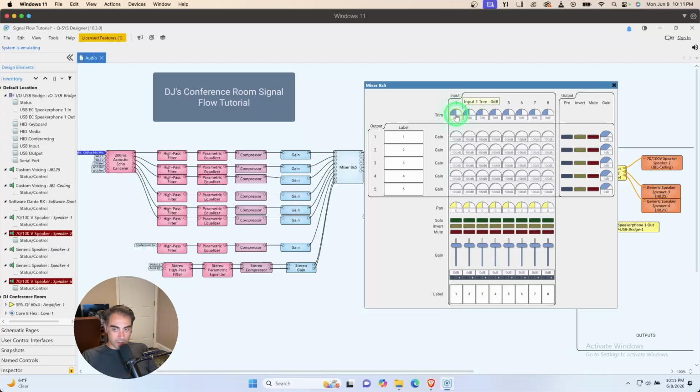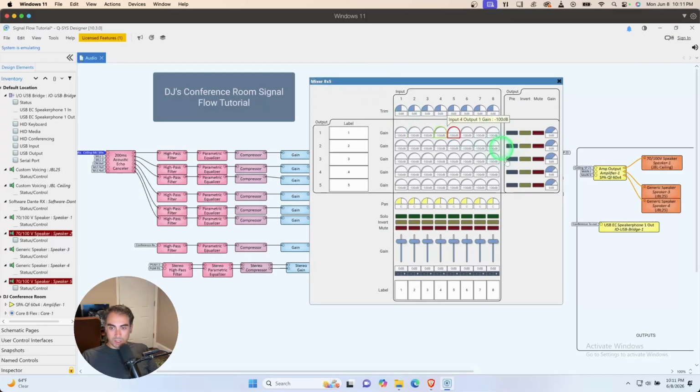Like, how on a mixing console your trim knob would be up top here, and then your post trim or head amp gain, and then outputs are going to flow kind of from left to right out here. So the way you can also set up this matrix as strictly mutes. You can set it up as cross points with volume. So this is just cross points with volume.